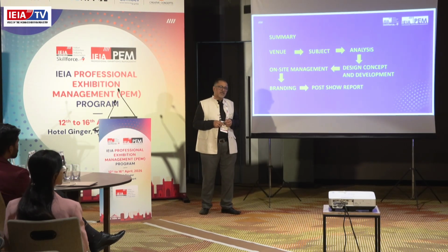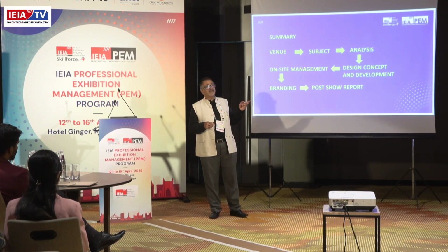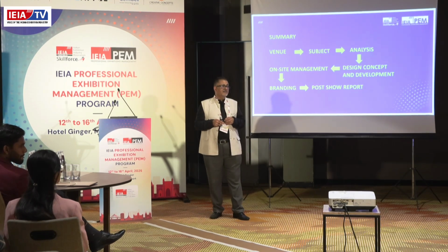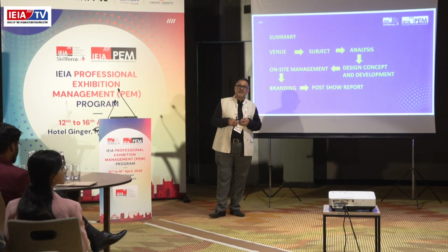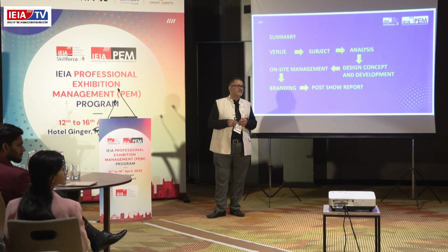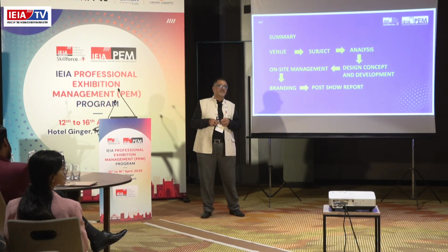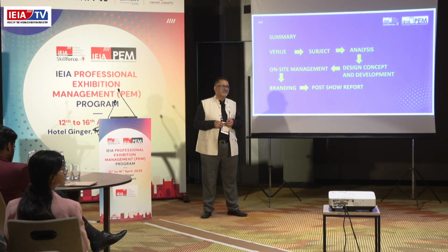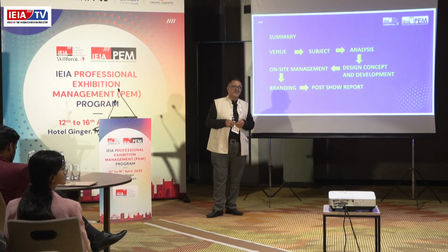Sachinji, if you can tell more on this. Certainly, sir. I fully agree. Plus there is the height available for getting the hydras in, because the boom height should always be added to the maximum permitted height of the installation. So if 4 meters is the maximum which you are permitting, add 2 meters for the hydra, and if you are permitting 6 meters, does that door permit 6 meters or not? You can be in a very tough position where you cannot do anything if the machinery will not enter. The entire blame will be with you.